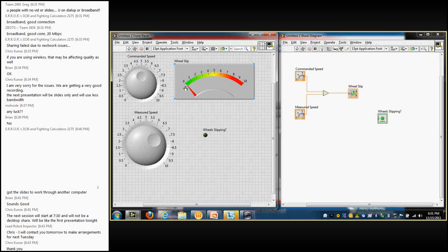One of the nice things about LabVIEW is you can always go in and change the value: just highlight and type a new value into the bottom of the meter. You can even do that while the program is running. So you could even rescale the meters on your dashboard if you wanted to. So now I can see that I can display more negative numbers. So 5 minus 9 should be -4. 5 minus 1 should be 4. I've written a program here that does a little bit of subtraction. So that's the very basics of creating a program inside of LabVIEW.